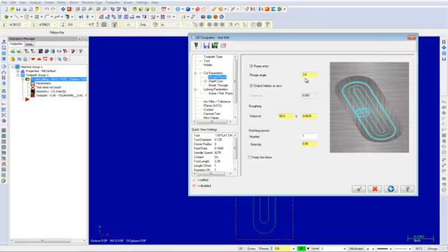Roughing step over sets the distance between cutting passes in the X and Y axis. Enter a percentage of the tool diameter or a distance. Finish passes allows you to set the finish cuts for the tool path. This number multiplied by the finish spacing value equals the total amount of stock cut by the finish passes. Setting the number of finish cuts to 0 creates no finish cuts. And finally, when Keep Tool Down is enabled, it does not allow the tool to retract between multi-passes.